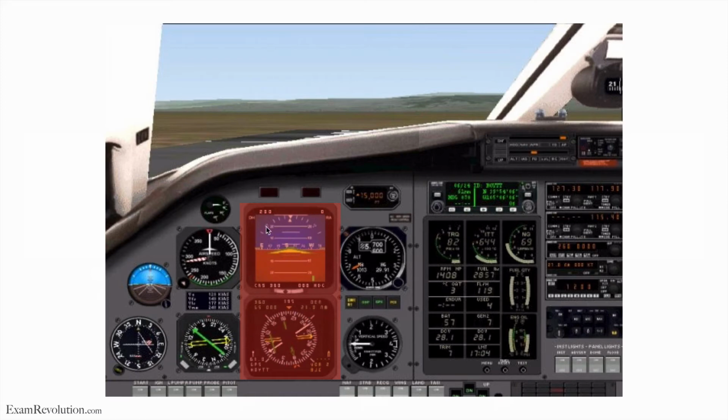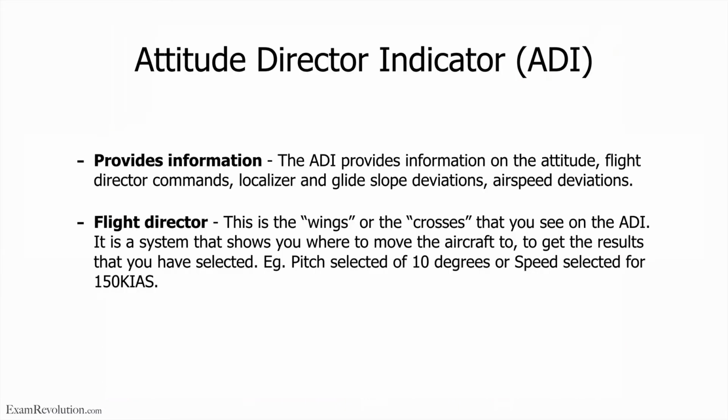So this is the example that I showed you right in the beginning of this video when I showed you the architecture of the EFIS. This is what I was referring to. Obviously with the mode control panel, you can change the settings on here if you want to. And where you actually use it the most is to change the settings on here. If you want to go into a plan mode to show your flight plan, or to show you a map instead of the VOR, or to take some of the information that is displayed on the side away, you might want to have DME and not ETA, or you might want to have the VOR2 and not VOR1, or whatever the case might be. I'm sure you get my point.